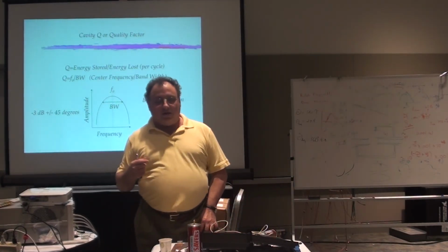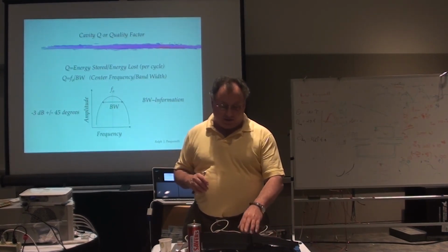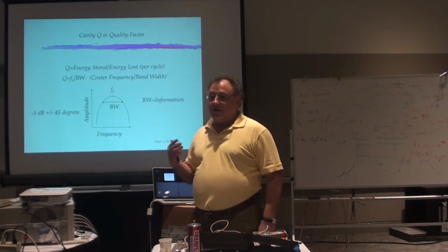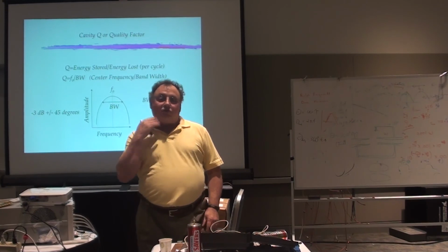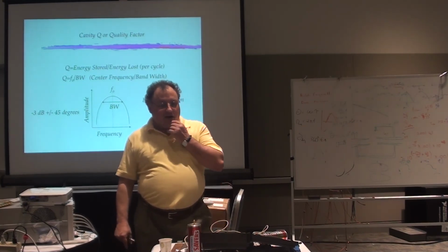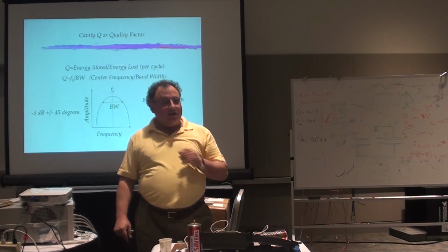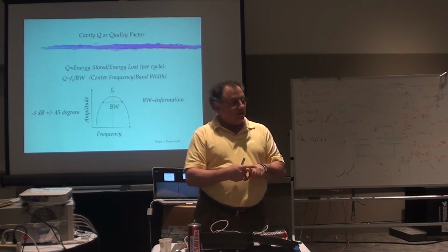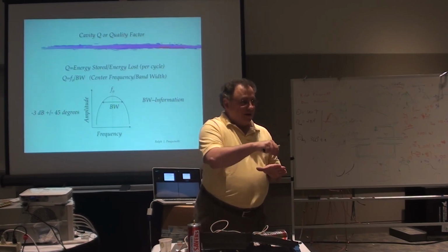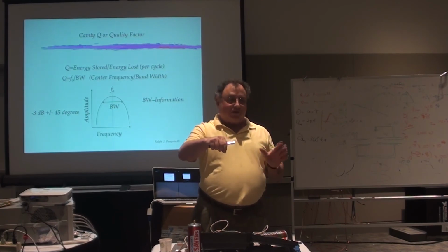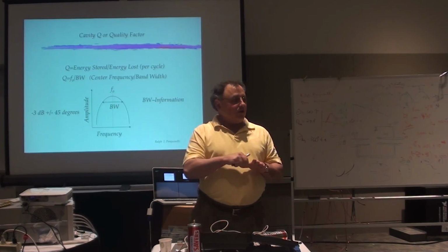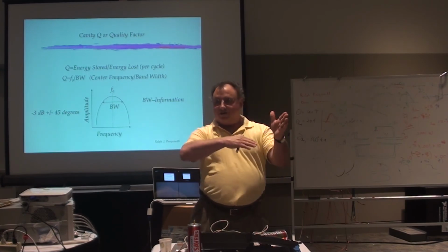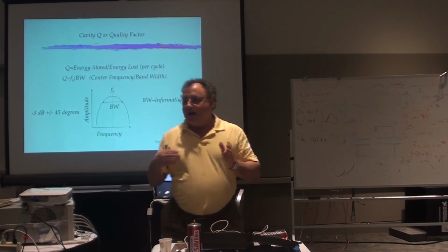The way things used to be done to be very accurate, certainly when I was even taking it, is you would actually plot what the response was in linear terms, and then there was a very clever device which I think I had one at work. It's called a planimeter, and a planimeter is a really interesting graphical tool that you set there on the paper, and it's got 2 orthogonal rolling wheels, and when you trace out any curve, no matter what it is, this ingenious thing that's probably been around for 200 years, when you trace around a closed curve, it gives you the area of the curve. And now that you know what your 2 axes are, that tells you the very accurate noise bandwidth.